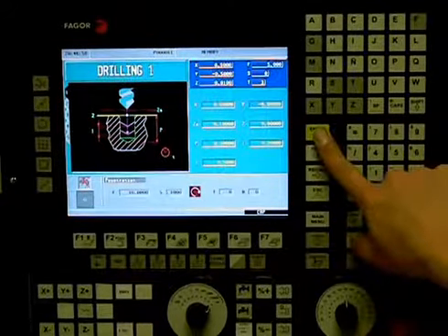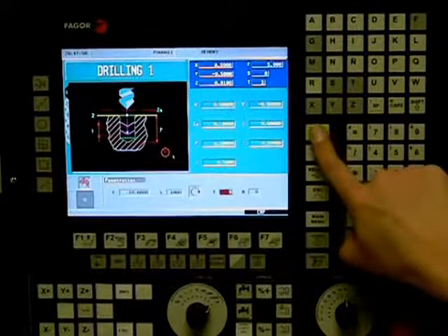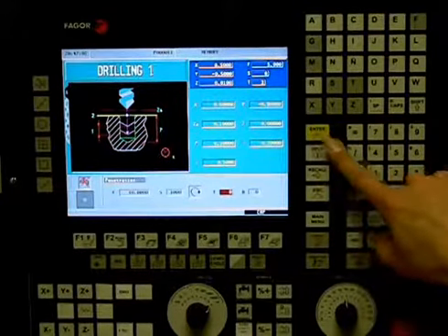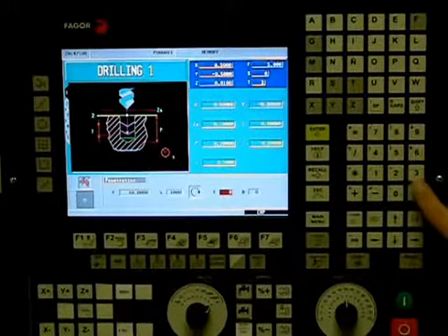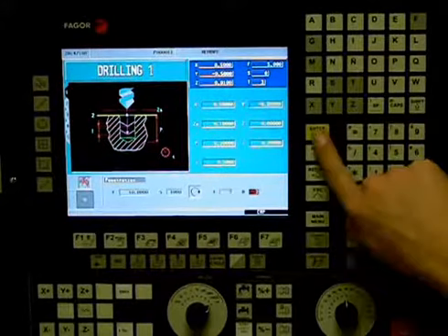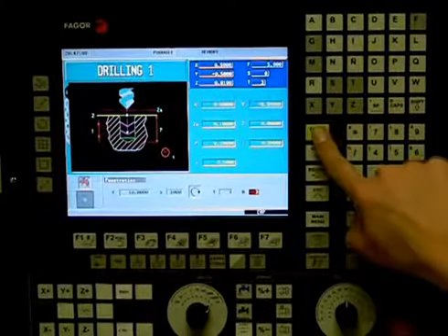You select your spindle direction. To toggle, use the half key. T is the tool number, and we will be using T3. D is the offset number, and we are using D3.